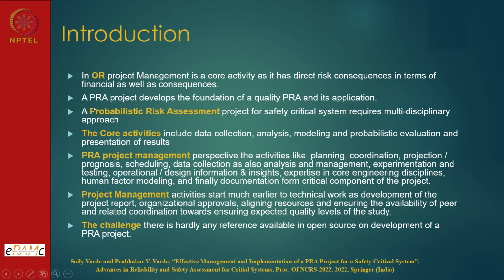My personal opinion is, if you want to give a quality PSA, at least 10 to 15 years of data should be available on the system, and if the data is not available, wherever the impact is high, live testing should be carried out. It will not tell the data correctly, but it will help us understand the robustness of the component we are using, and then whatever vendor specifications are there can be converted into data.